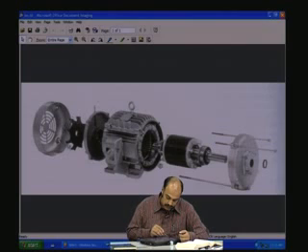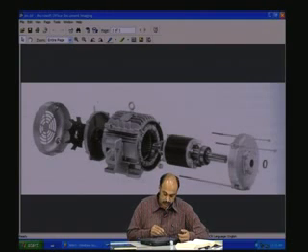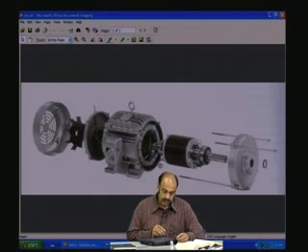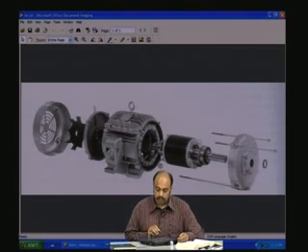And here you could also see beyond this face plate there is something mounted on the shaft, and that is a fan, and beyond that there is another enclosure, a covering for the fan. So this fan is to provide cooling for the machine, that is, this is an air-cooled, enclosed air-cooled induction machine. So this is how the various parts of the induction motor would look like. This is a squirrel cage induction motor.